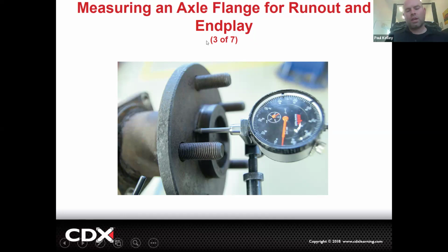ASE has questions like that. You got to look at not only the dial indicator, you got to see, are they saying it's getting turned? That'd be run out. Are they saying it's going in and out? That would be end play.